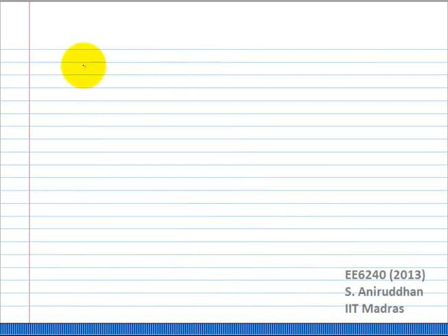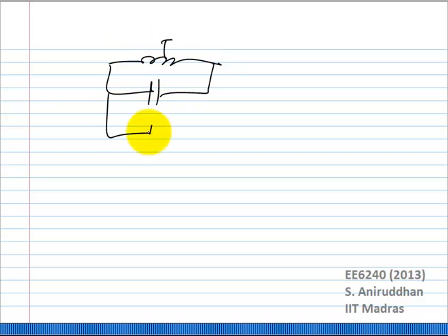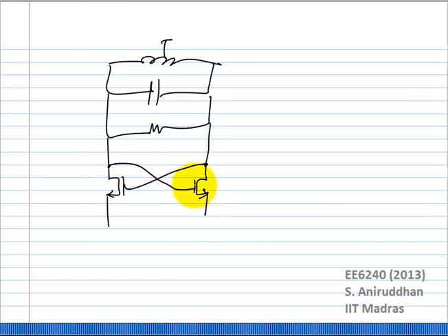What he says is, we'll take the cross-coupled NMOS only cross-coupled pair, but it doesn't matter really. So I have some IT plus some noise here, correct? What kind of noise? I'll have device flicker noise and device thermal noise.